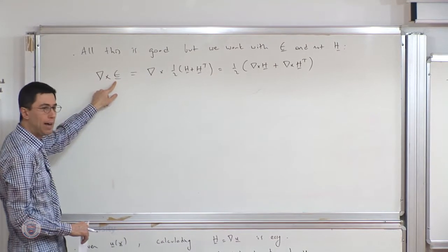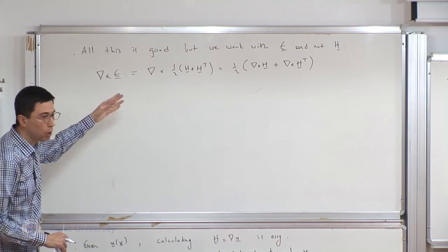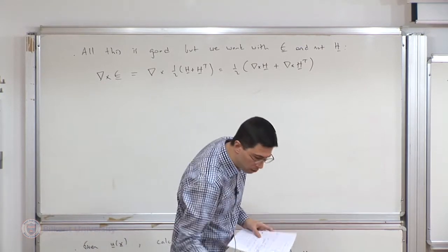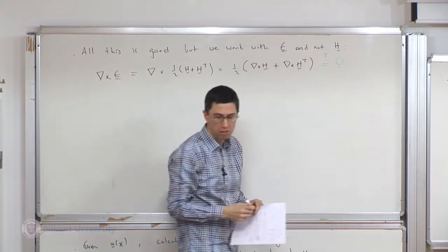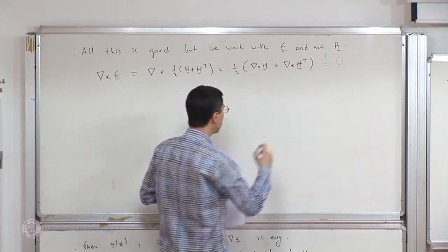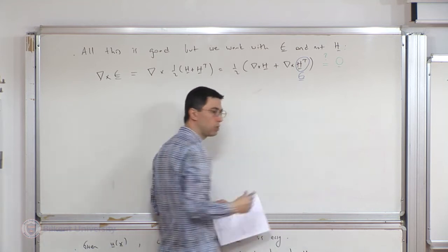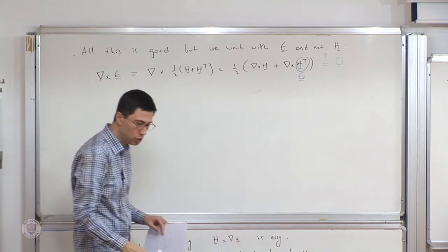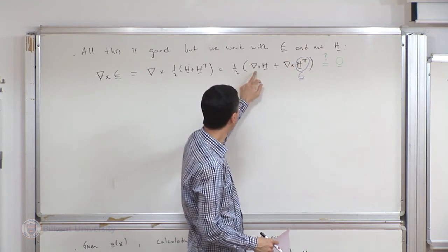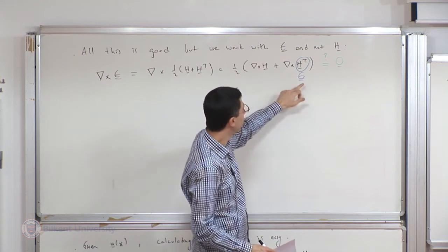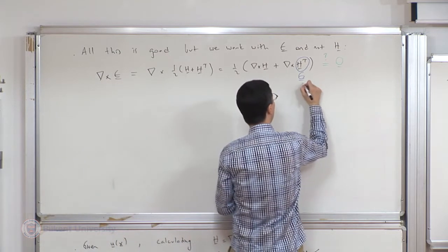So the epsilon that I have must be somehow compatible with the existence of a displacement field. So first, I check its curl, see what that gives me. Perhaps my question is, is this equal to 0? It may or may not be equal to 0. And to make that argument, let me call this, just for the time being, G. I'm rarely going to need that notation, but H transpose, I call G, so that the transpose does not confuse us. So I have the curl of one matrix, the curl of another matrix.